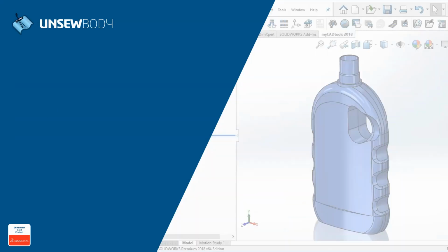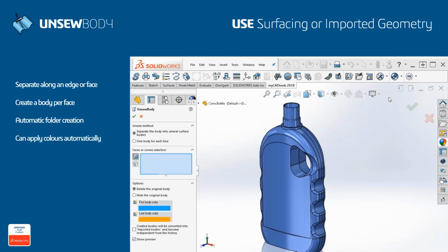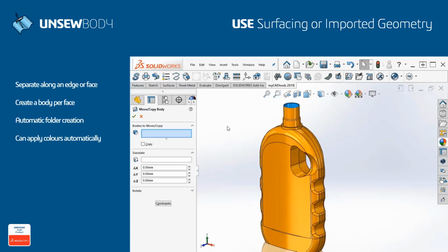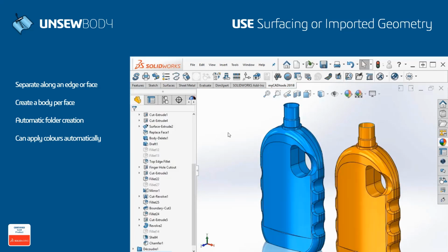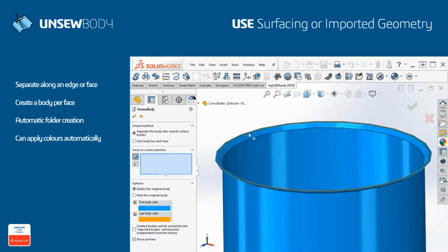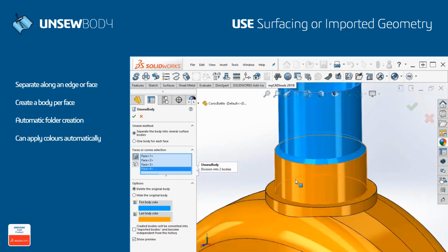Next up is UnSewBody. This tool is perfect for anyone dealing with imported geometry or creating surface models. SOLIDWORKS includes the facility to sew surfaces together with the knit command, but doesn't have a facility to separate them. This is where UnSewBodies comes in. The tool can be used on either edges or faces and will separate a single surface body into multiple surface bodies. This can be useful for a number of situations when working with surface models or imported parts.